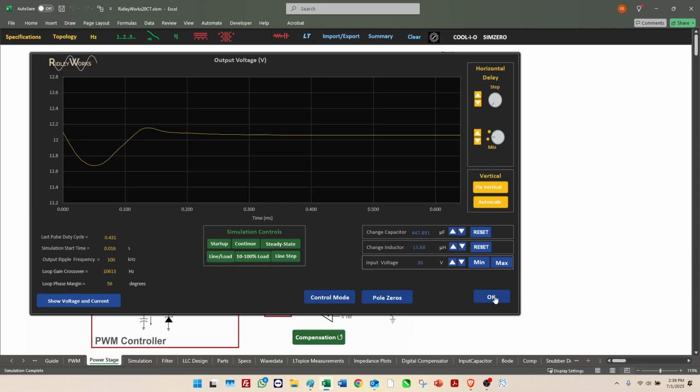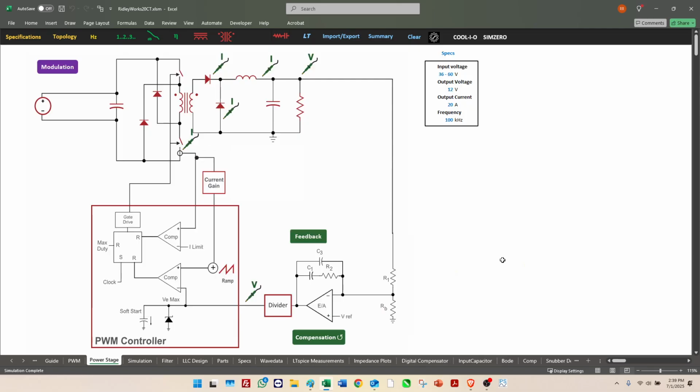Now, we're not trying to be something like LTspice. This is not a general purpose simulator. This is just for PWM converters only. They have very special characteristics in the power stage, and they have very special characteristics in the controller. But even so, it's still a fifth order system that we're trying to simulate here. And we've had this simulation algorithm in place for well over 20 years now. And as I say, nobody else has been able to reproduce what we're doing here, because it is pretty remarkable.